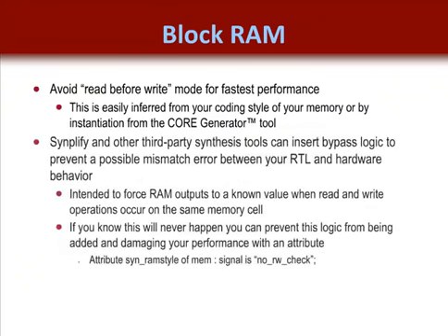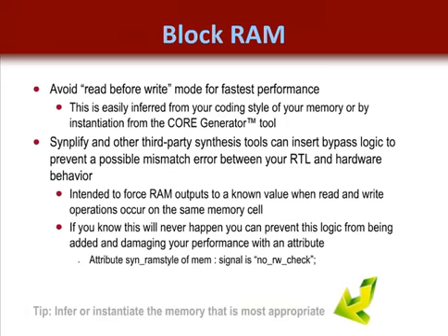Synthesis tools such as Synplify insert bypass logic around the RAM to prevent the possible mismatch between the RTL and the hardware behavior. This extra logic is intended to force the RAM outputs to some known values when collisions can occur. If the designer knows that these collisions cannot occur in his system, the synthesis tool settings can be used to prevent bypass logic from being added to the application. This extra logic has a negative impact on the memory performance and it is therefore recommended that you prevent its addition.